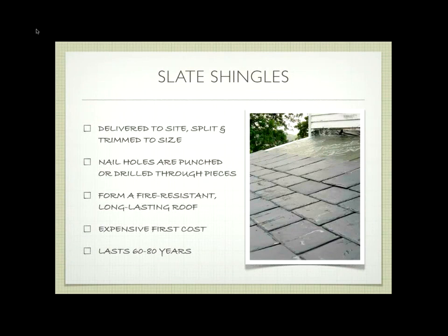So what about slate shingles? Okay, you've probably seen this. If you put it on your house, good for you. Not something I could ever afford to put on my house. It's stone, so it's a very resistant material to fire. It's a very resistant material to weather, so that's great. They can crack. They come to the site split. They can vary in thickness a little bit. Usually they have holes drilled through that allow you to attach nails.